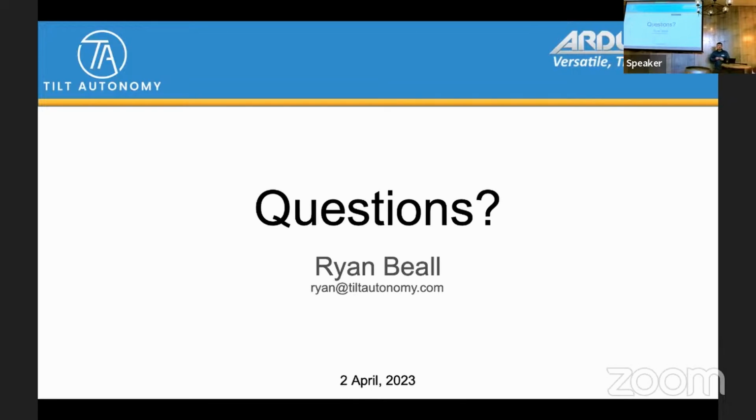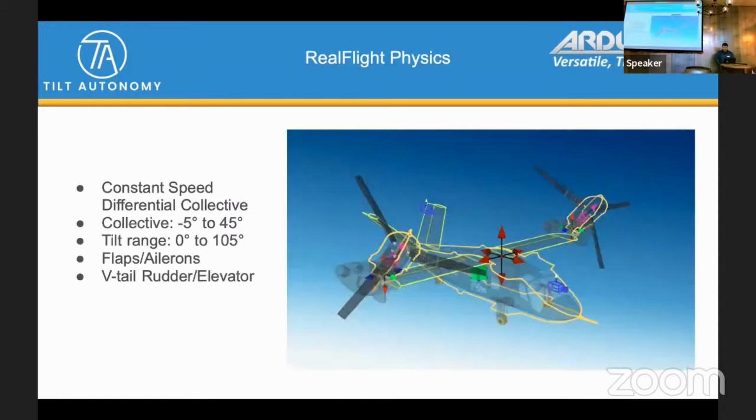Specifically in RealFlight, as far as I know, there's no way to draw an airplane in RealFlight. They expect you to import some shape, and then from there you can really easily outline the physics scaffolding that you saw right here. All of the yellow lines represent the physics scaffolding. There's even a button you can click to essentially take the visual image that you imported, and it'll wrap the physics scaffolding for you. So if all your dimensionality and scale is correct, it'll wrap that generic shape as best as it can. Sometimes it gets it wrong, but oftentimes it gets it fairly close.